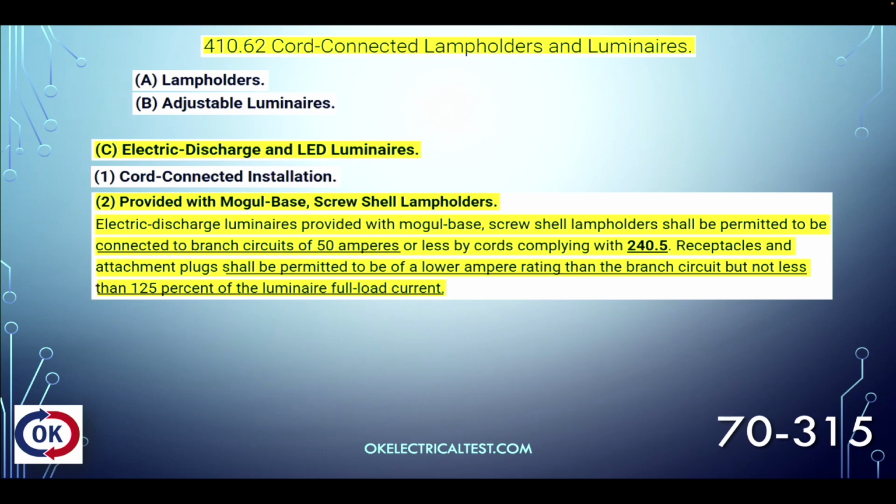So I can have a receptacle on that mogul base screw shell lamp holder, that's perfectly fine, but it needs to be at least 125% of that luminaire full load current.